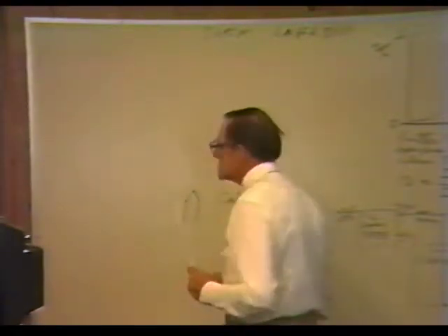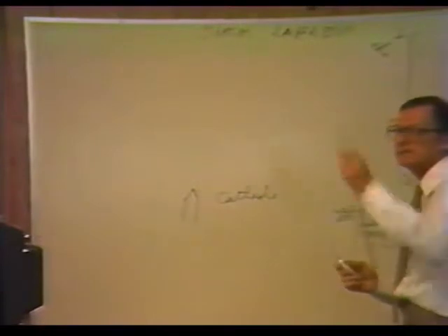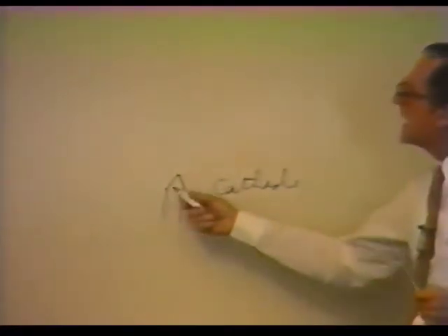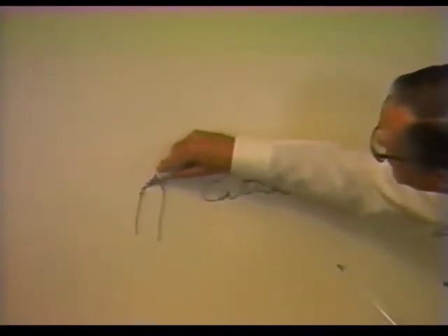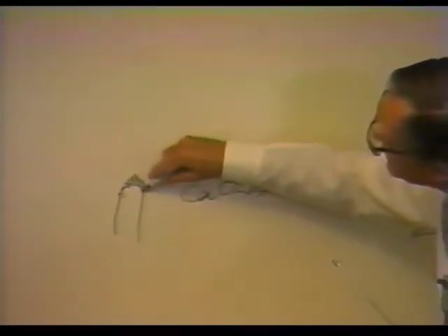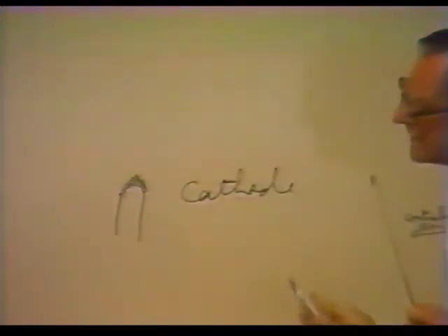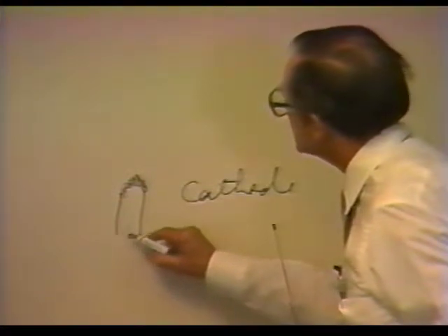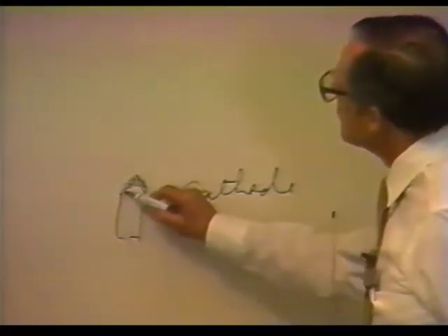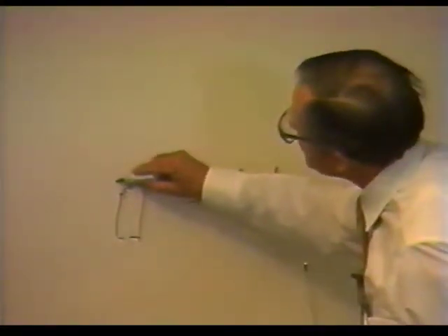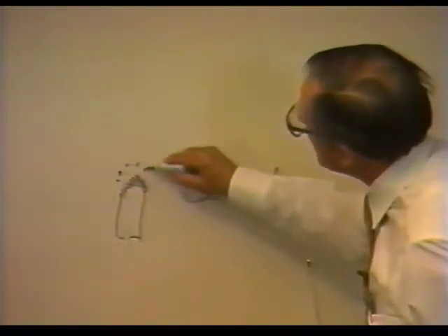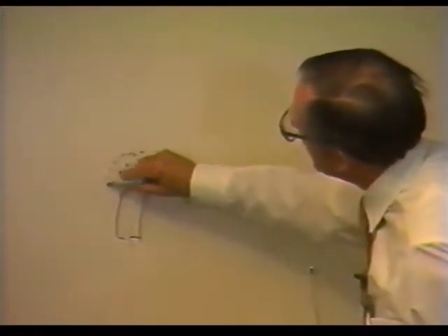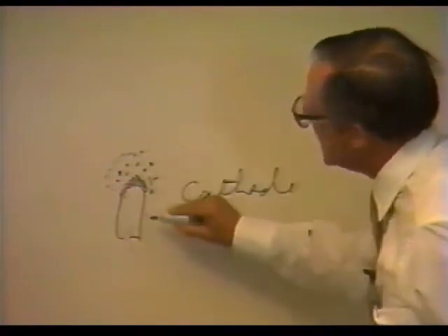Now, the cathode was a piece of wire like a wire in an incandescent lamp. And it had coated on this wire some kind of earth metal, which was very rich in carriers, in electrons. And when you heated the wire, put a current through it, with a battery, or however else you wanted to do it, the wire got hot, and these electrons, and I'm using the word electrons, boiled off around this cathode.